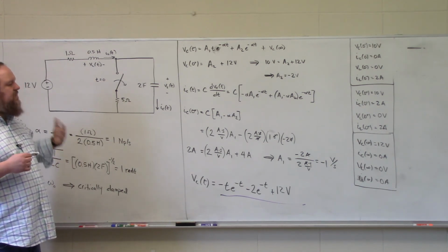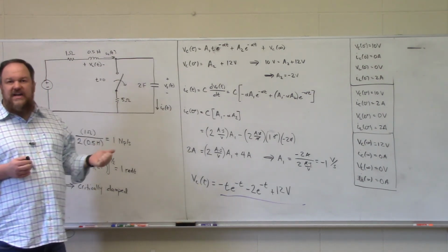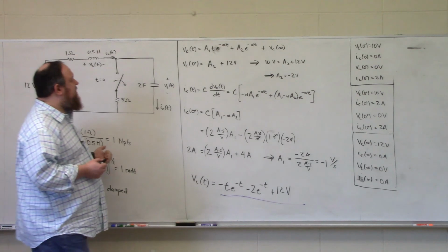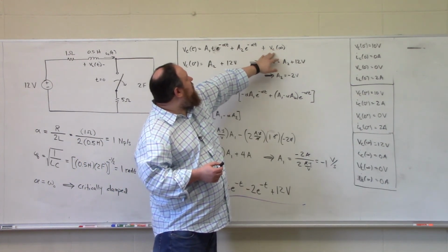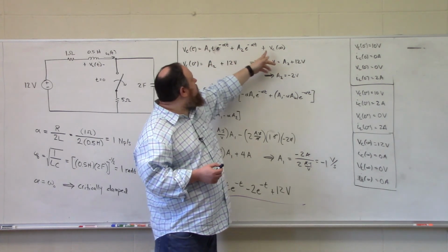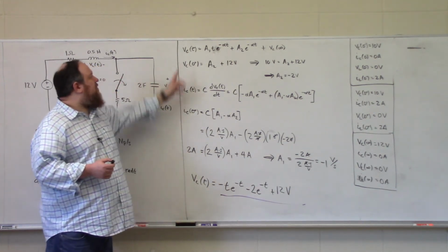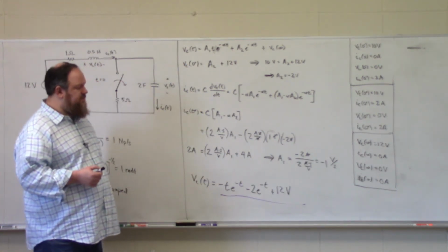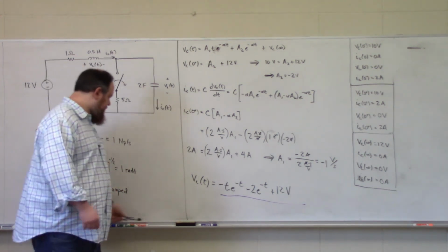The only changes that we made versus a natural response problem were analyzing the circuit at t is equal to infinity and then making sure to remember to include whatever our quantity of interest, whether it was the capacitor voltage or the inductor current, goes to at infinity in our first equation that develops our system. Other than that, the methodology is the exact same as we've done previously.